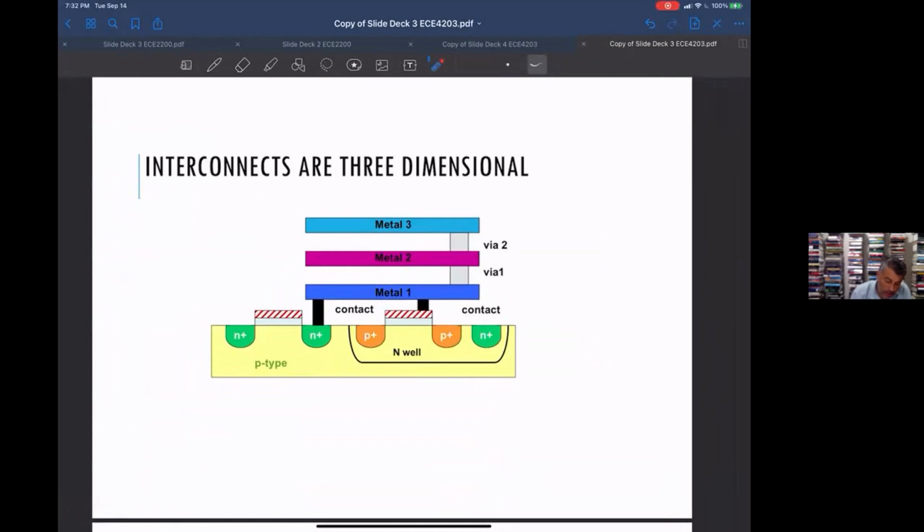The layers on top of the transistors are the metal layers. So you need to have these different layers. There's dielectric in between. But if you want to make contacts between these, you need to open up connections through the dielectric, and those are in the form of these things called contacts and vias. Vias are basically connections between the metal layers. A contact is any connection from metal one only.